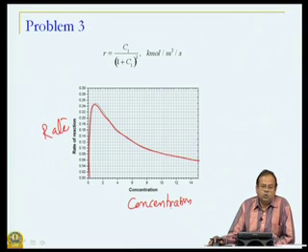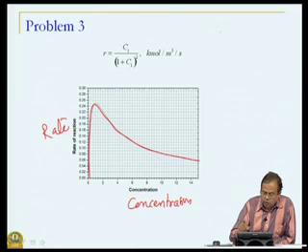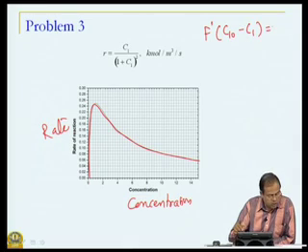So, let us try to take a look at the solution of this problem. Isothermal. So, we just need to look at the mass balance, and if we take again our mass balance, F prime into C10 minus C1 is the rate of the reaction, right, into the volume.